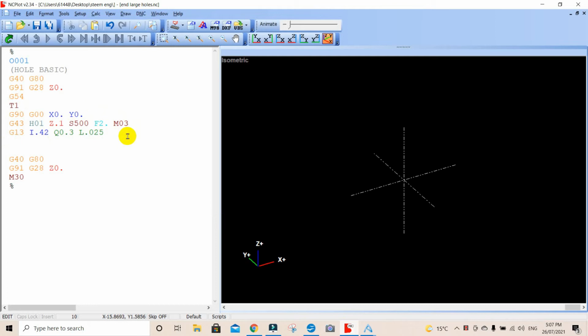Now we want a finish depth of negative Z. I believe this needs to be a negative figure, but I'm not really sure. It's a matter of putting it up on the machine and giving it a shot. We'll go negative 0.125 or 1/8 of an inch. And we also need to factor in the tool we're using, if we're using a 1/8 cutter,